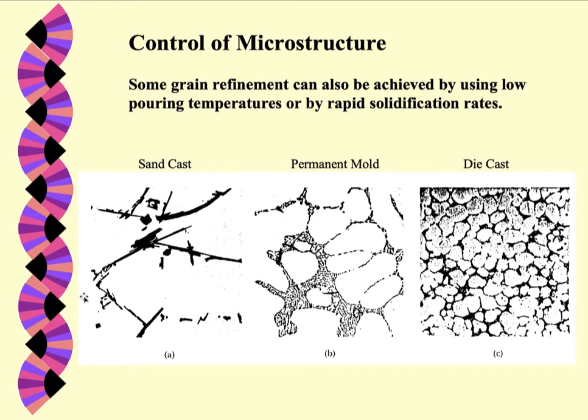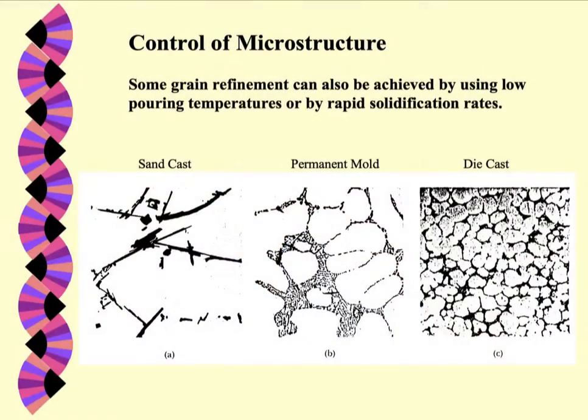So here is what, okay, if we took a sample of aluminum, we polished it smooth, and usually you don't even need to hit it with acid or anything. You just look at it on the microscope, and what you're seeing is the silicon, the beta phase on that phase diagram. Okay, so this is the primary silicon that comes out, and then the white areas are primary aluminum.